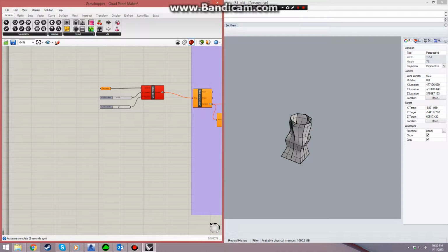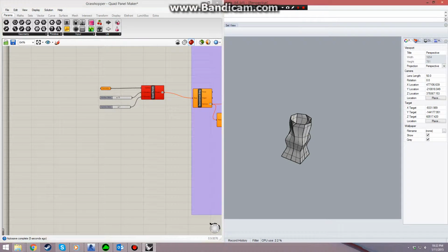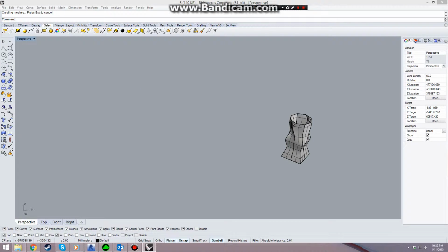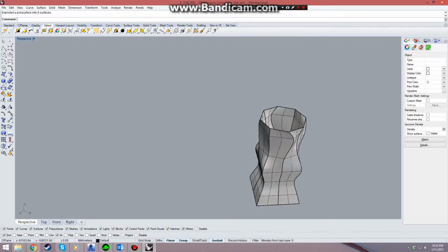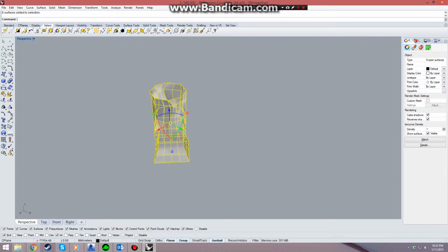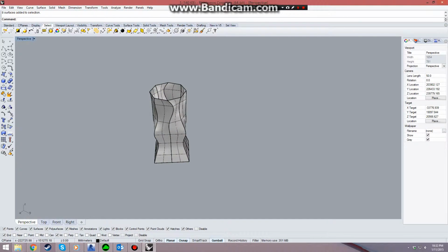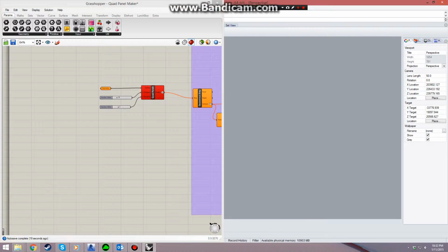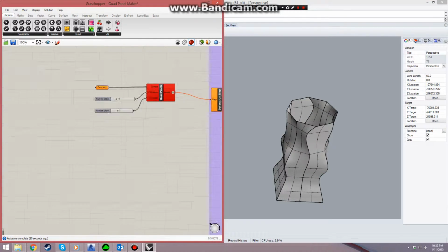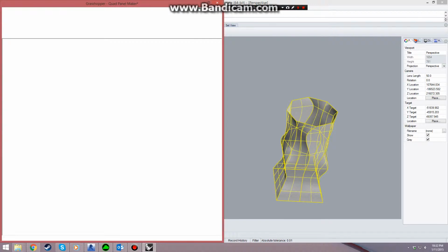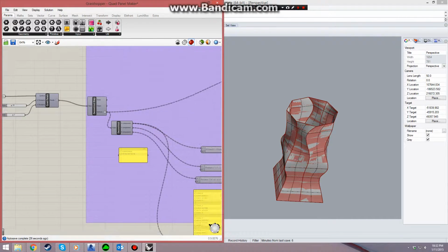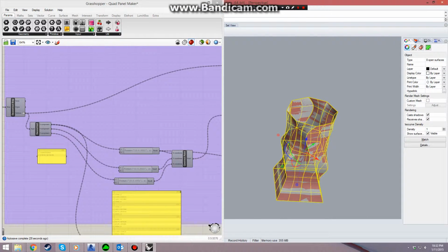I have attached all this in the Dropbox link. What you want to do in Rhino first is, this is a poly surface. You want to explode that first. This will give you 8 surfaces, and you want to set the multiple geometry in, and this should work.